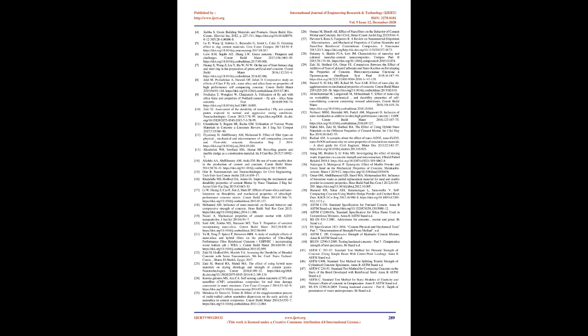4.5.2 Thermogravimetric Analysis, TGA. Thermogravimetric analysis is a quantitative measurement that records the change in specimen weight caused by dehydration, decomposition, and oxidation of its material at a heating range from 20 up to 1000 degrees C and a rate of 10 degrees C/min. TGA analysis was applied to assess the effect of mineral additions on the microstructure of the paste matrix, and to track the changes in its hydration phases.